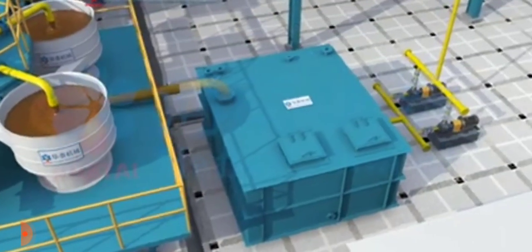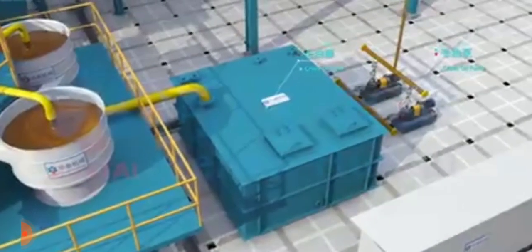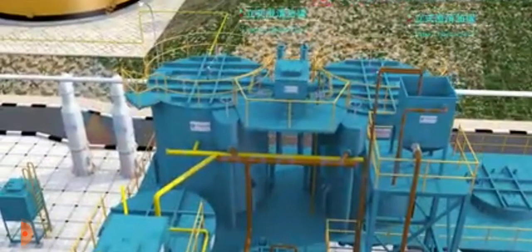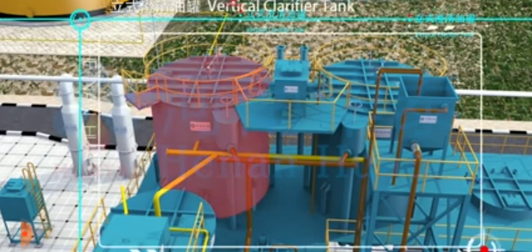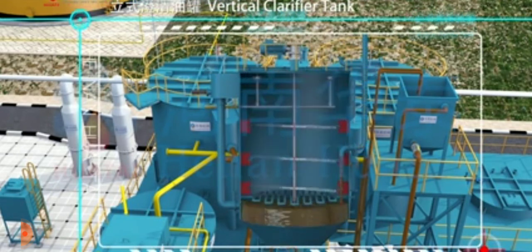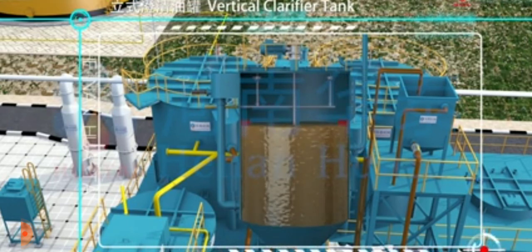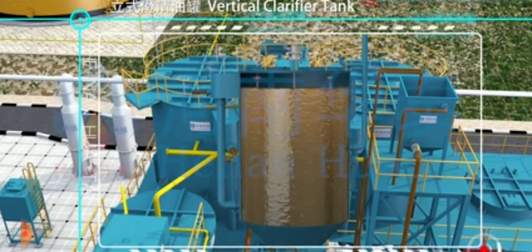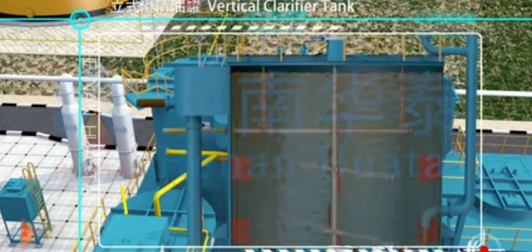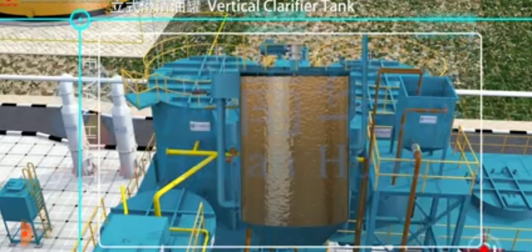Filtered crude oil enters the crude oil tank for temporary storage. A crude oil pump conveys it to the vertical clarifier tank. Through heating, stirring, and settling treatment, clear oil stays up while dirty oil and water settle down. Clear oil goes through the oil skimmer and enters the pure oil tank.